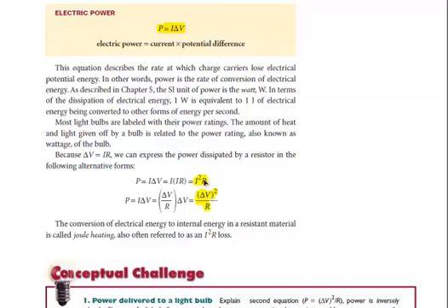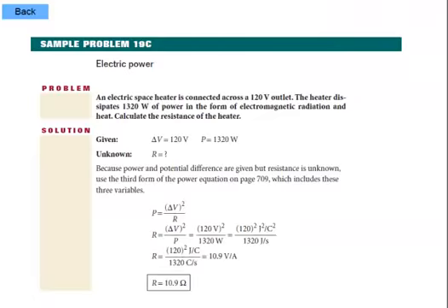If you have high current with the same resistances, you're going to wind up getting a lot more friction. So unfortunately, a great deal of that power is going to be simply dissipated as heat energy and not maybe useful work. Now that idea is called Joule heating, or I squared R loss. For something like a space heater, toaster, hair dryer, things like that, it's great because we want heat from them. But for other devices, we want more energy delivered as useful energy, and therefore sending it at a higher voltage avoids the I squared R loss problem.